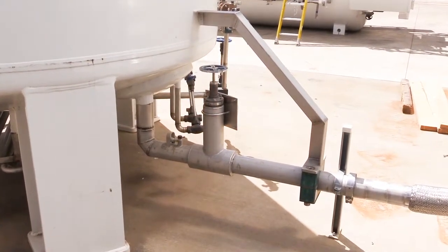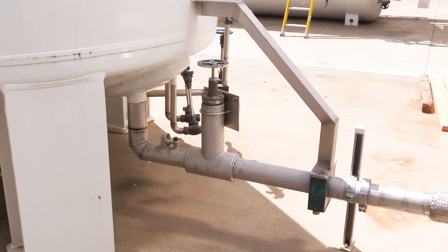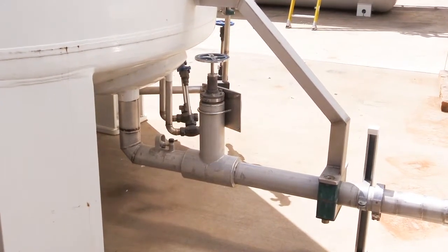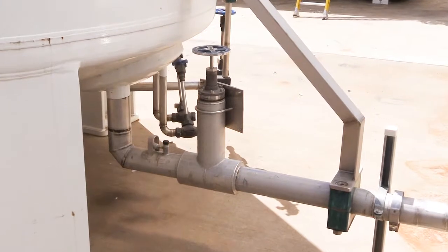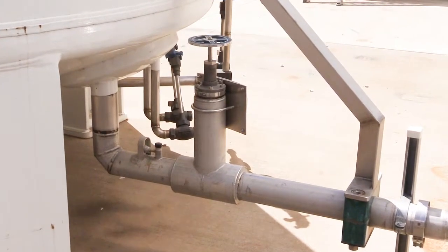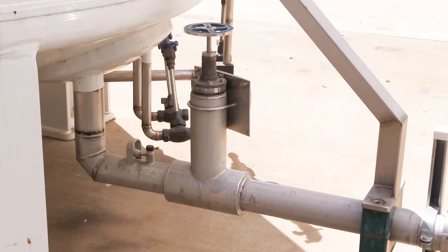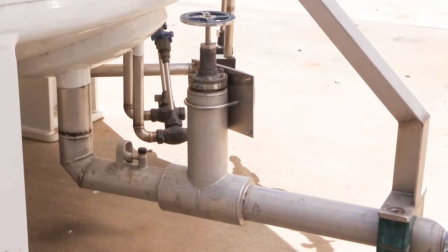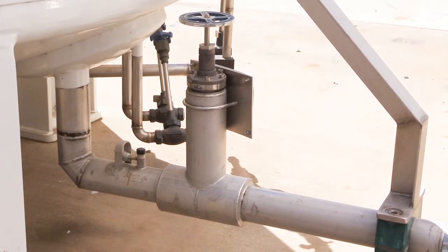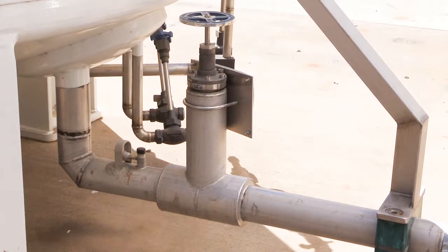Some cryo vents actually have a shutoff valve on the outlet, requiring them to be treated as a device requiring a relief valve. Manual valves, check valves, regulators, actuated valves, or any items that can stop flow or allow flow in only a specific direction typically will drive the need for a relief device to be incorporated.